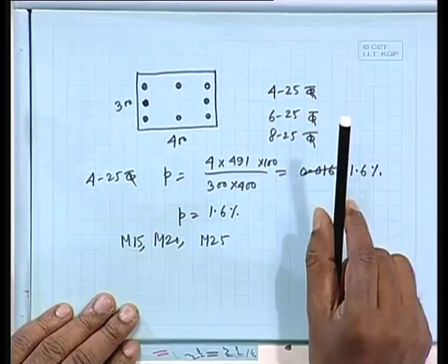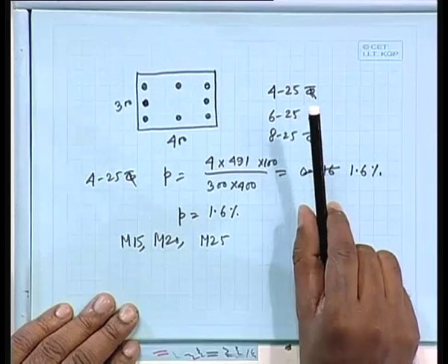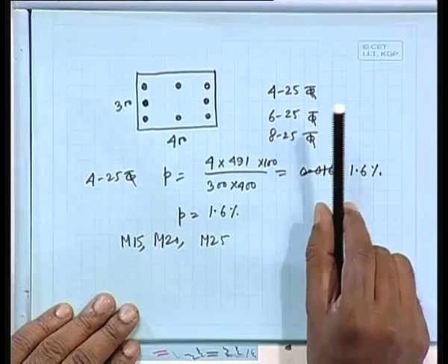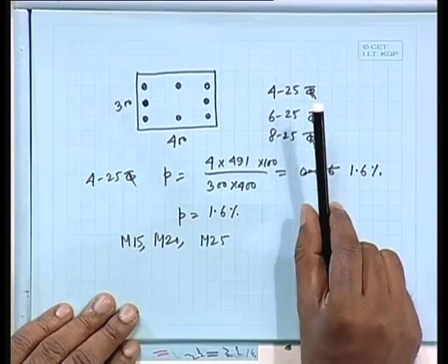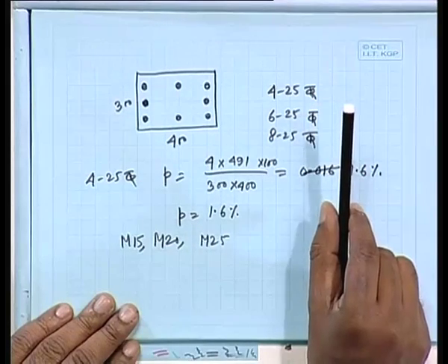For preparing the chart, wherever they need say your FCK value, there you assume that they are using concrete grade say M20. But that is not the case. So when I am doing the computer design, I shall obviously use whatever grade of concrete you are using, so let us use that grade itself. So that way we do it.